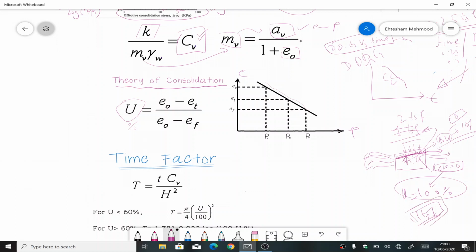So you get the point: initially the specimen is at a certain height, then we apply a load, and delta U increases equal to that load. Then with time, and depending on the permeability of the soil, delta U starts dissipating as water moves out of the loaded area. While the water is moving out, soil particles are rearranging themselves, and they reduce in volume.